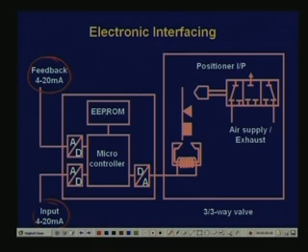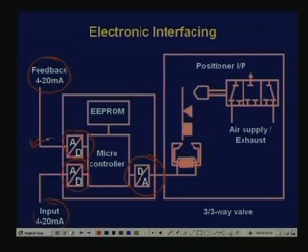It may be something else also, and then these signals are acquired in a digital controller. Finally, the digital controller computes the necessary force that must be applied for control to the valve. That is output through a D to A converter. These are A to D converters, because these signals are analog, so they have to be converted by A to D.